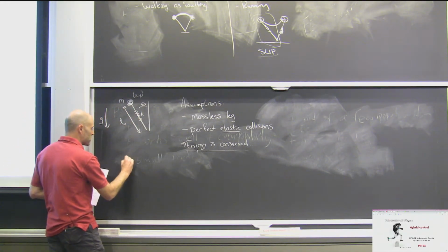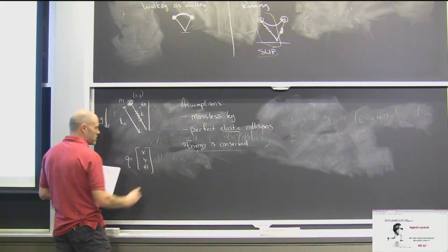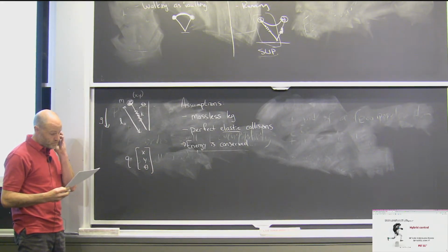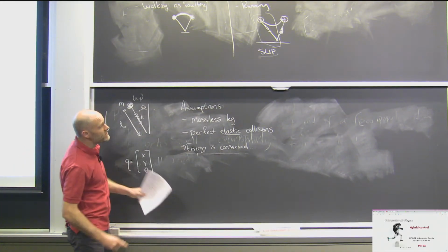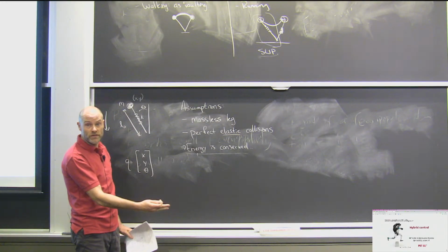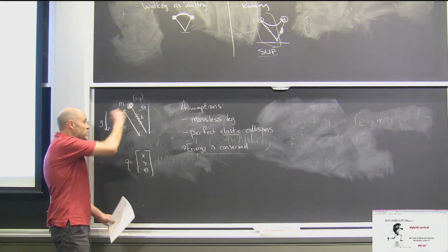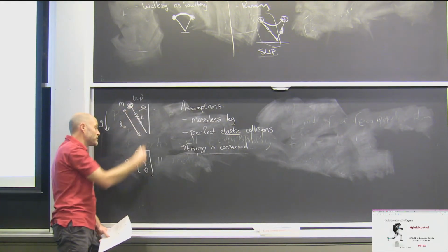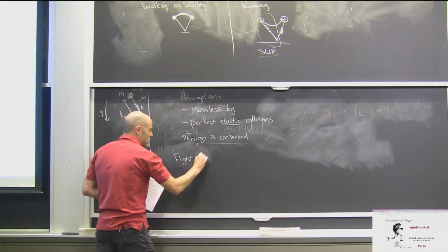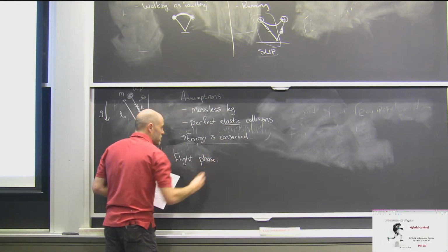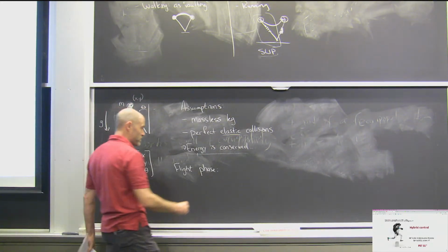All right, so my coordinate system is, by default, x, y, and theta. It's still hybrid, right? It still has that same picture of having this impulsive event. It's just that it's now an elastic collision. So when my foot hits the ground, I'm going to instantly change my dynamics. I'm going to actually break up the dynamics into the flight phase, which is just a ballistic path of my center of mass, right? Just the ball flying through the air.